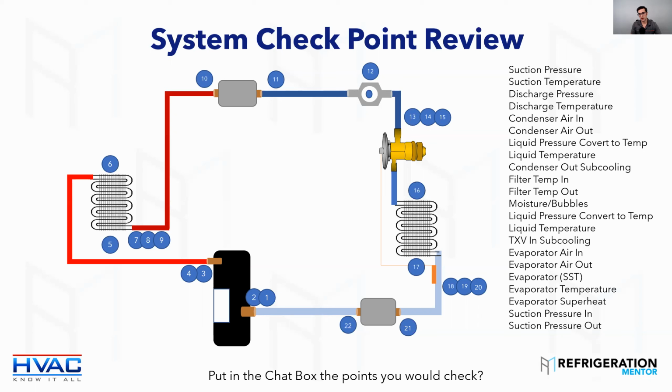These ones would be called cores. So you can actually take the filter dryer apart and put a core in and pull the core out, or put the pleat filter in and take it out. So maybe that's not where you were going with that, Justin, but I just said it anyway.